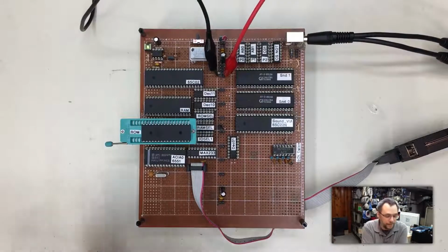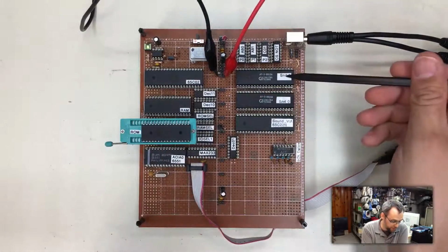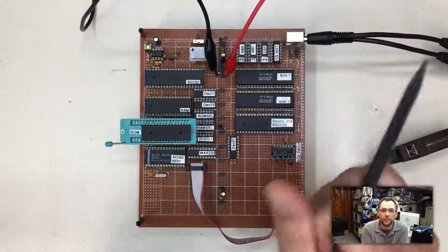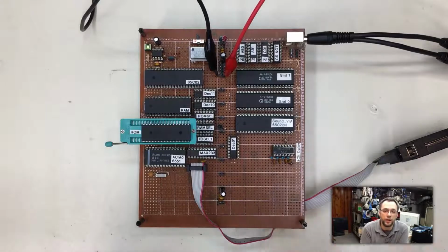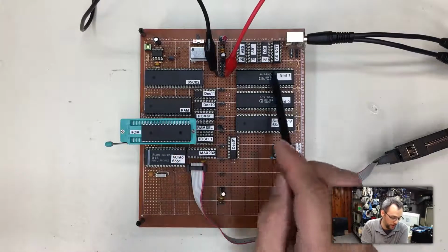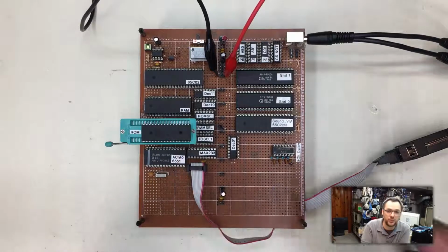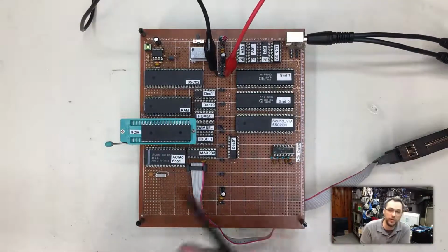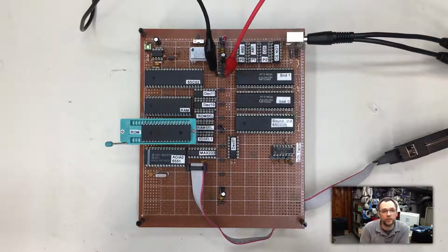Chime sound's pretty easy. Basically, I set multiple tones on both of the chips and set them with an envelope and just set them to free run and then come back. So the CPU is doing no work, or very little work whatsoever to make that sound. It just says, hey, sound chips, go do it. And they fade out and do the thing automatically, and the computer is immediately responsive upon power up.